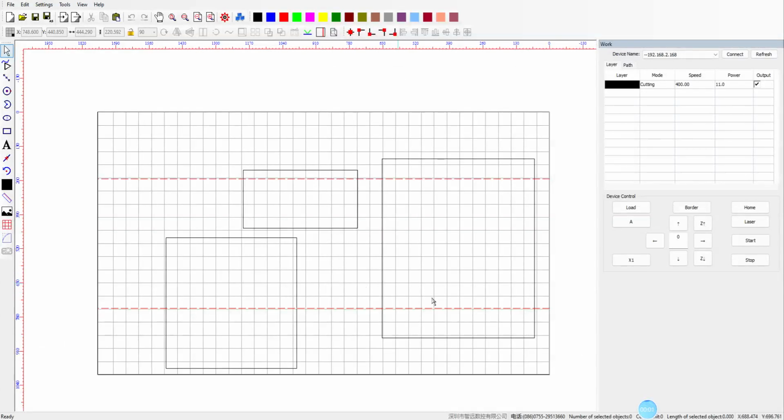In this video, it's about showing how to create a shape in the cutting software to cut. The shape can be inside the table size, but it can be over range of the cutting hand 1 or cutting hand 2, because this machine has 2 cutting hands. Cutting hand 2 will cut this top dot line to the very bottom. Laser 1 will cut from the top line to the bottom red dot line in this area, so that won't go over each space, each docking position.